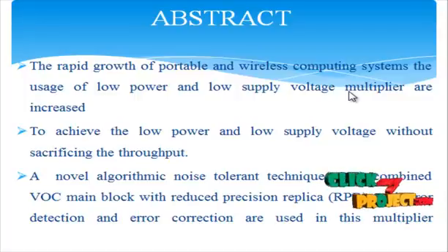The system makes use of partial product weight analysis to find the approximate computation vector for a more precise RPR design. The proposed fixed width RPR multiplier not only performs with higher SNR but also with lower circuitry area and low power consumption. In order not to increase the critical path delay, the system restricts the computation circuit in RPR so that it must not be located in the critical path. As a result, the system can realize the ANT design with smaller circuit area, low power consumption and lower critical supply voltage.